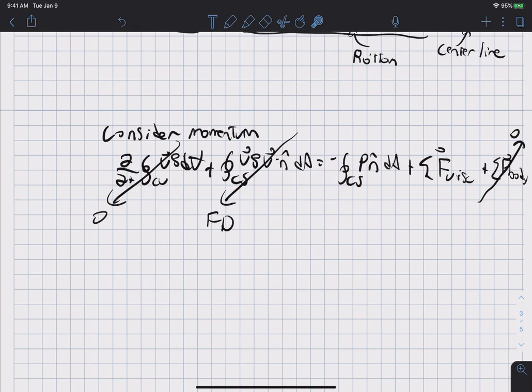and I'll prove this result here. So we just draw a little control volume, and it doesn't need to be differential. We're assuming that rho is constant, and so we have rho v dot n hat times an area going out on this face, and rho v dot n hat times the area on the other face.